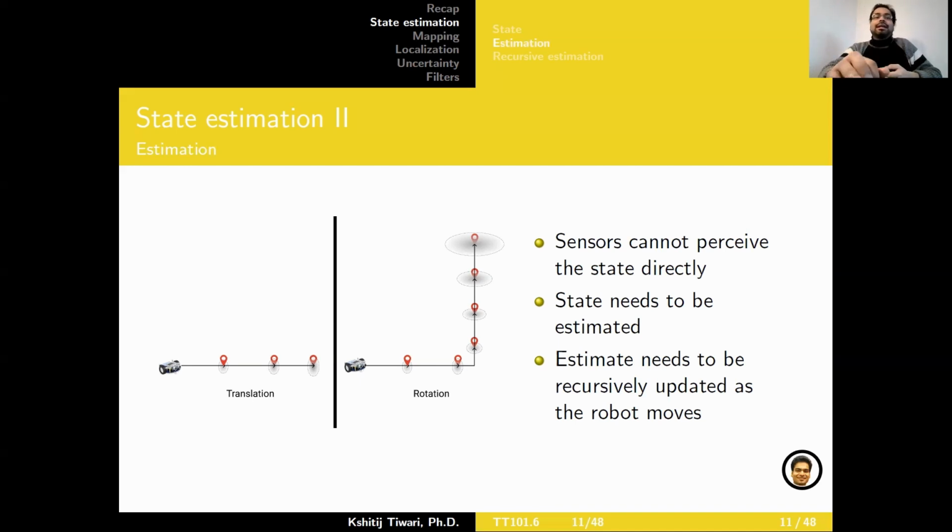An interesting fact to note here is that in this example that I've shown you, the robot is moving and we've considered two cases independently. In one case, it is just translating in a straight line. And after every certain amount of time elapsed, you're trying to estimate the current pose of the robot. Let's say that's the state for this scenario. And the ellipse that I've drawn around this is the location uncertainty that you have at that position, because you're moving forward and you are not 100% sure, but you're kind of sure that somewhere within this region is where you should be.